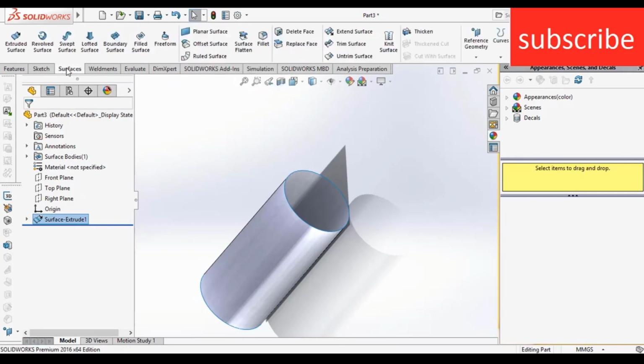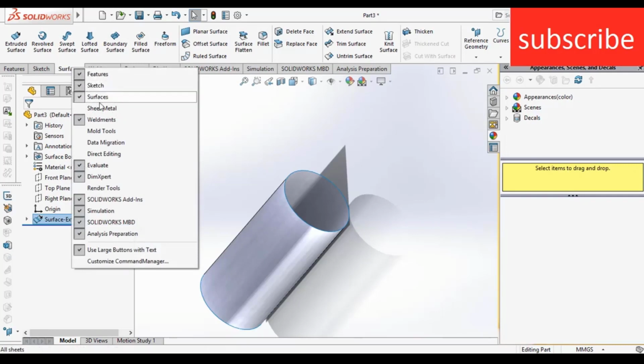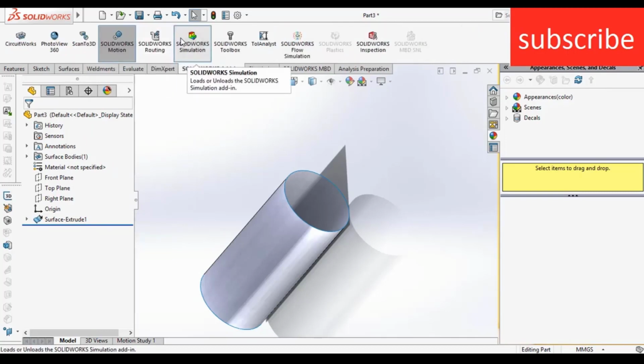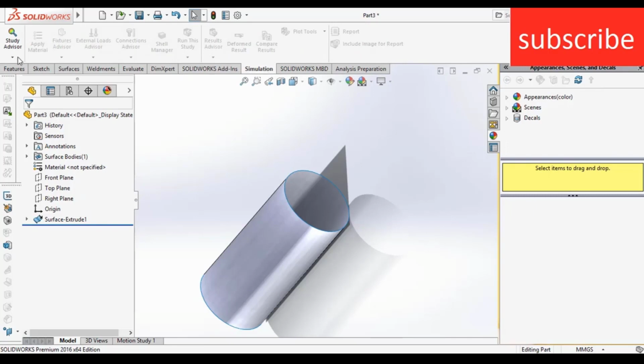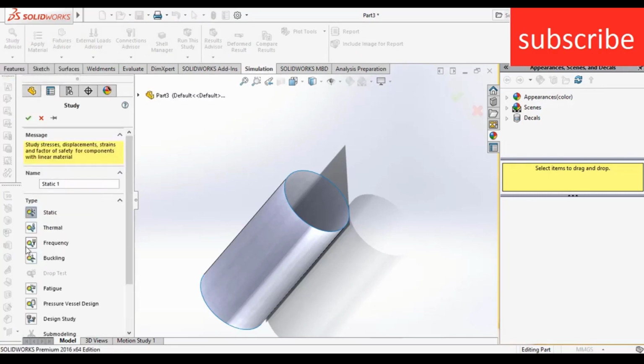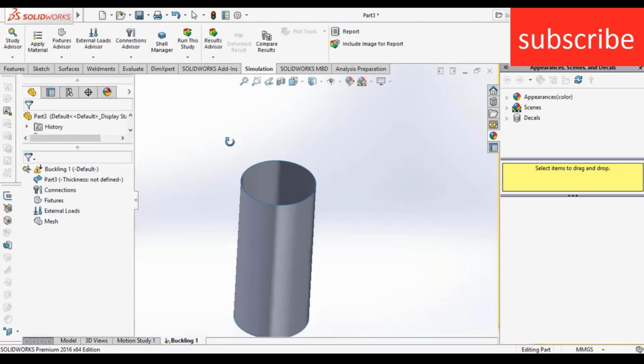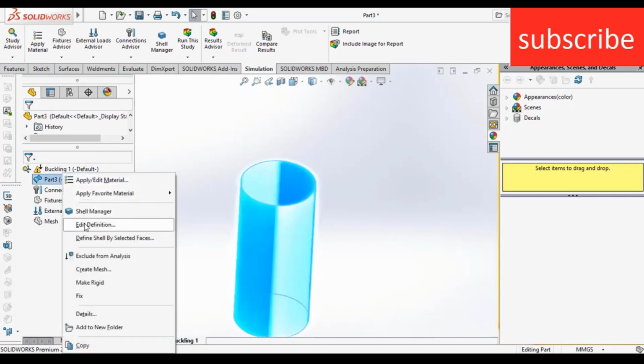One more thing, some people might not be able to see surfaces in their tab. So what you can do is right click on here. Here you see different kinds of things, for example sheet metal, weldments. If you don't see surfaces, just click on surfaces and you will get the surface tab. After that click on SolidWorks add-in, click on SolidWorks simulation, go to simulation, click here, click on new study, click on buckling, click OK.